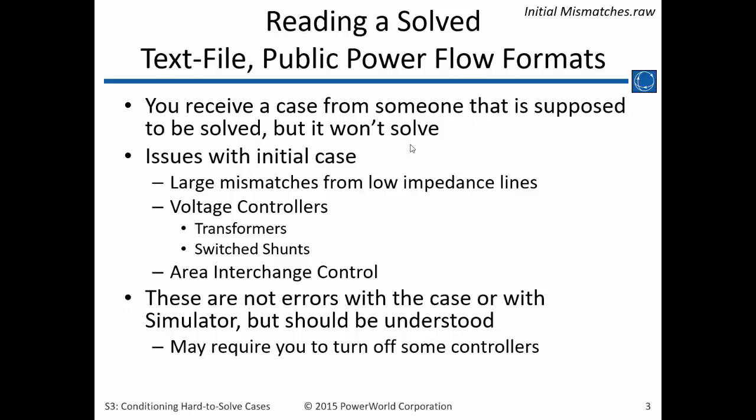And area interchange control. Oftentimes we don't know, was the initial case solved with area interchange control turned on or not. These are not errors with the case, and they're not errors with Simulator either, but you do need to kind of understand what they are, because it may require you to have some interaction with the setup of the power flow solution before you try and solve it for this model when you load it in.